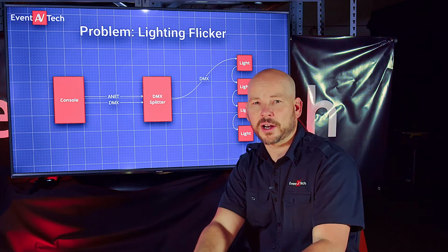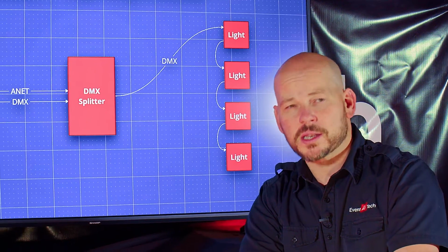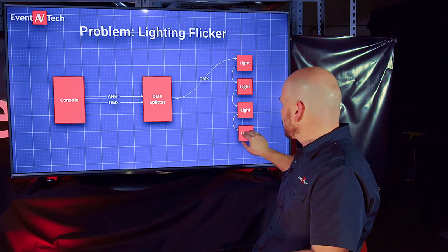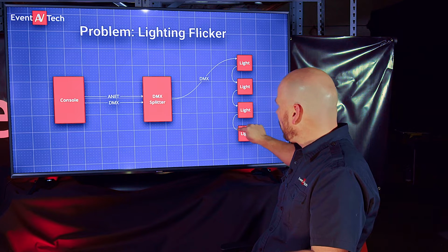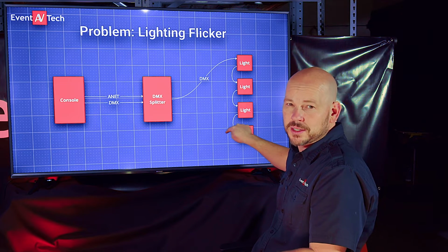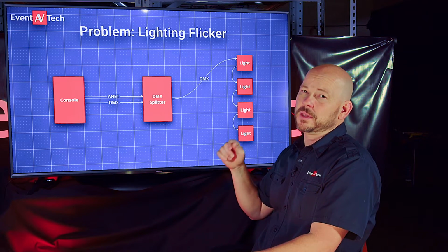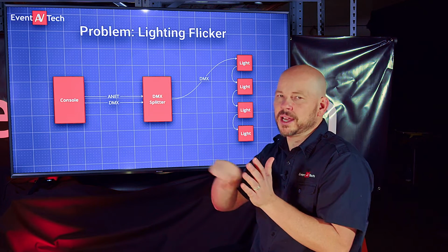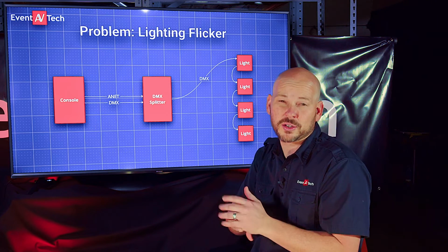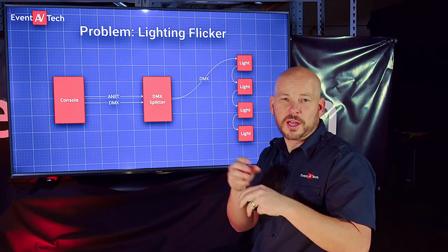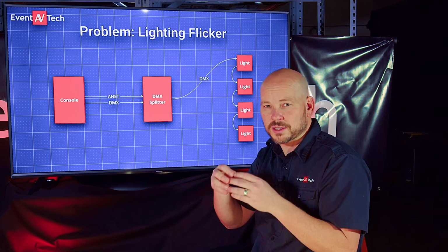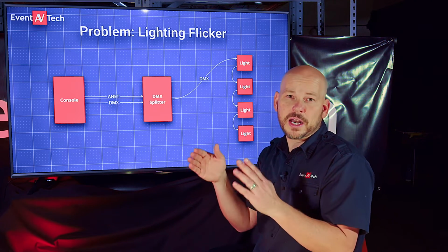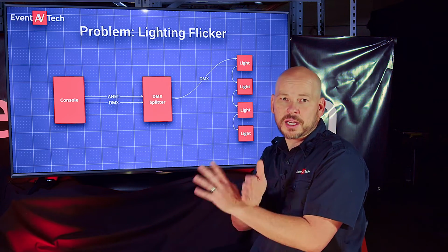And we had given them the wire diagram of how to hook everything up, but when they turned everything on, there was a ton of flicker. The way I addressed that flicker issue is I started checking all of my connection points and made sure that they wired up the light fixtures the way that we had designed them. And now we're not talking about a traditional 3-pin XLR. We're actually talking about LED strip tape, and there are a lot of conversions into converter boxes. And inside of that, I began to discover that at some point they swapped the negative and the positive.